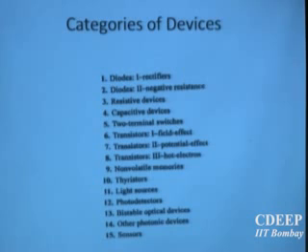So what does resistance do? It consumes or dissipates power, I square R loss. Is that correct? So if you have negative resistance, what will it do? It will generate. So there are devices which generate power. This is slightly a misnomer, but we'll explain. There are devices like Gunn diode, TRAPATT diode, IMPATT diode, avalanche diodes. These are essentially generators.